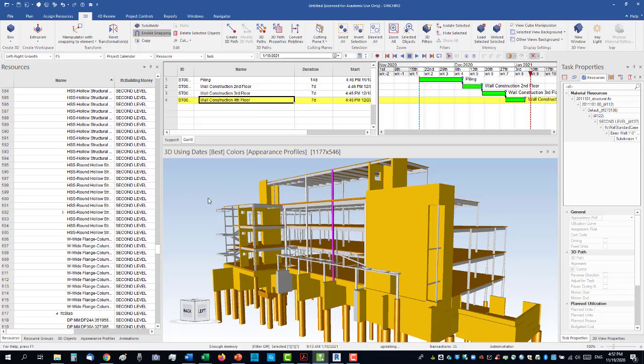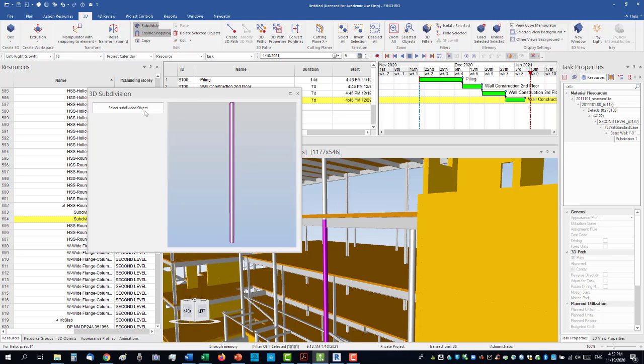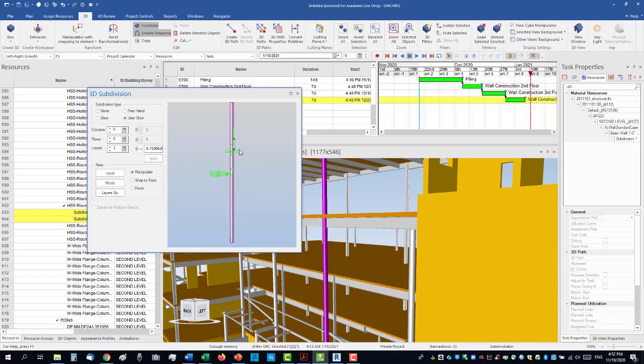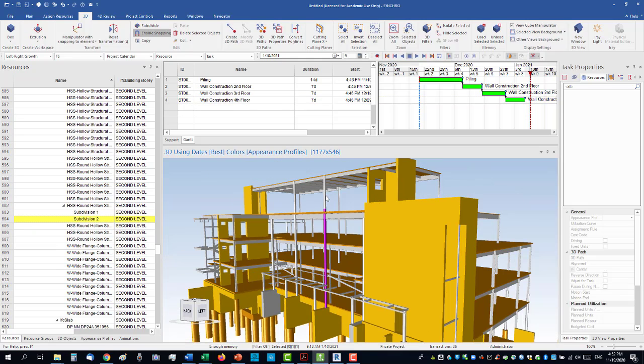So if I close and then unselect that, let's see here. Now I split it for the first 3 stories. Typically it goes above the slab. So this means I need to go back to the subdivide, select the whole column here, and then move it a little up, close, unselect, and now I see it's a little up, so that element here will come by itself.